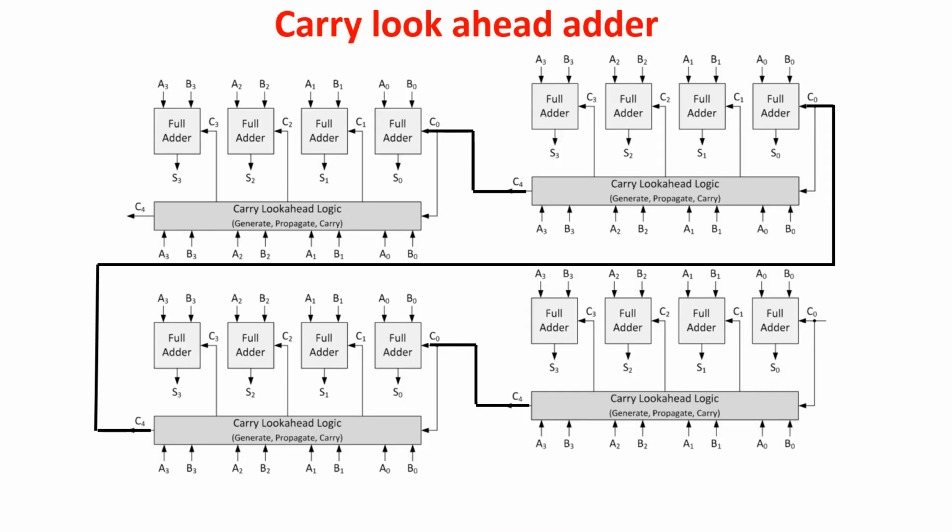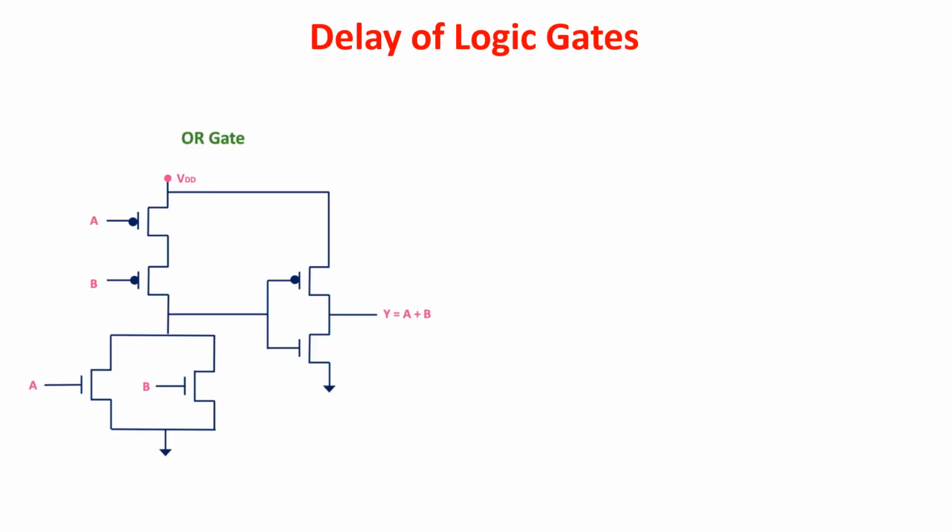Remembering that a logic gate is slower the more inputs it has, you usually prefer to limit the number of bits to 4, thus using blocks of 4 bits. In this example we had two 16-bit numbers using blocks of 4 bits. Using gates of 5 inputs is quite slow.